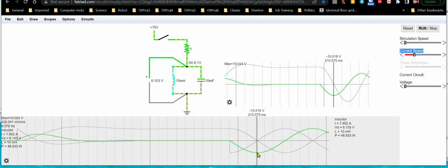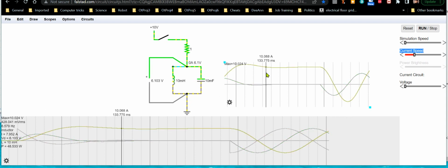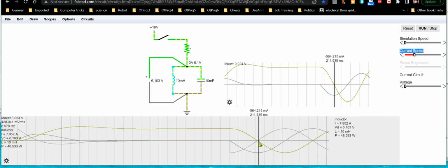Now the inductor has a voltage across it, because remember, inductors will instantaneously generate a voltage that opposes a change in current. Even though it's got 0 current, the inductor wants to keep it that way. So once that capacitor becomes king, it immediately generates a field, basically equal and opposite.